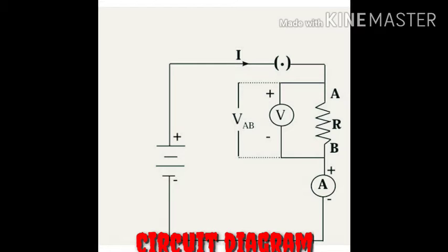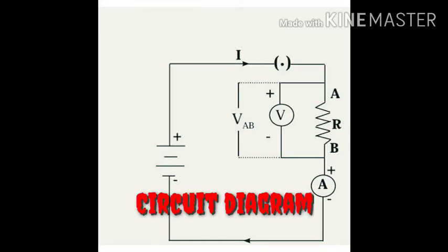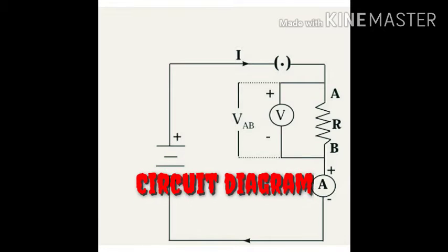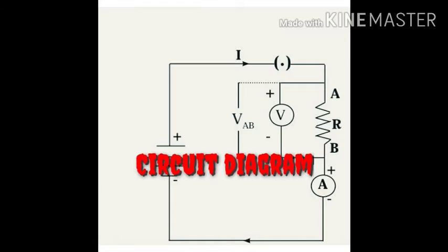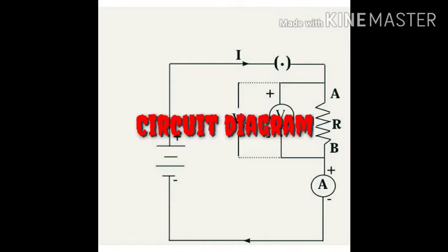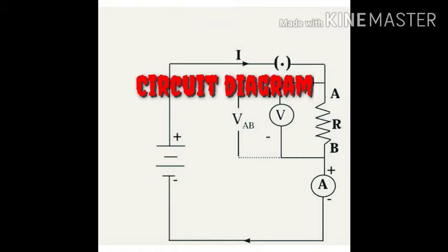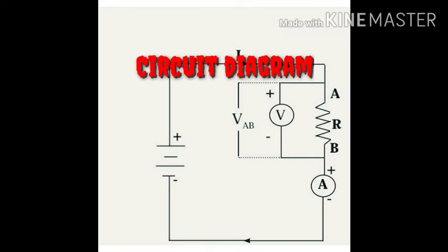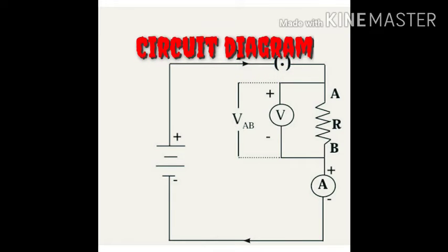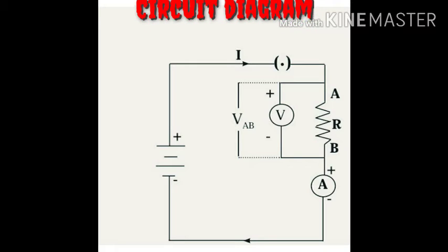Connect the circuit as shown in the figure. After taking the components with proper values, measure the current I. Also measure the potential difference VAB between the two ends of the resistance. The potential at A is higher than the potential at B, as the point A is connected to the positive electrode of the cell and the point B to the negative electrode of the cell.